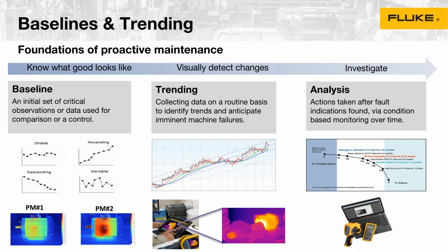So when we talk to customers about establishing a program, we say, look, do this on a constant basis, always at the same time, same application, and almost the same physical location. If you look at a motor, maybe put an X 2 feet in front of the motor, so that regardless of who takes the measurement, they're going to take it almost at the same location, pointing at the same spot on the asset. And so you need to start trending this over time. Then you will definitely see some of the benefit if you have an increase or decrease of temperature in a particular asset or location, and then you can start making decisions on that.